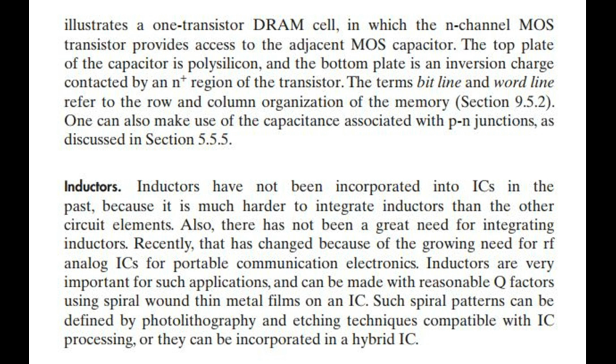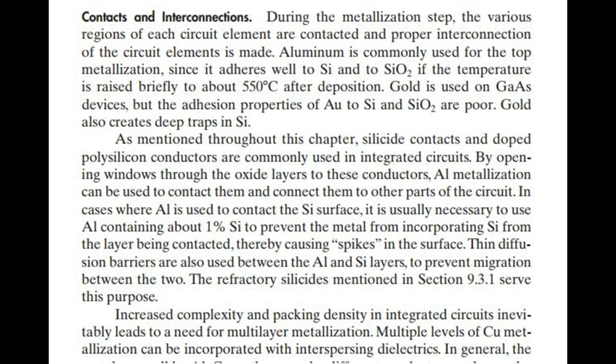Inductors are very important for such applications, and can be made with reasonable Q factors using spiral wound thin metal films on integrated circuits. Such spiral patterns can be defined by photolithography and etching techniques compatible with integrated circuit processing, or they can be incorporated in hybrid integrated circuits.